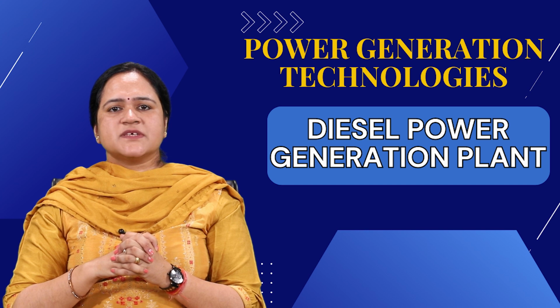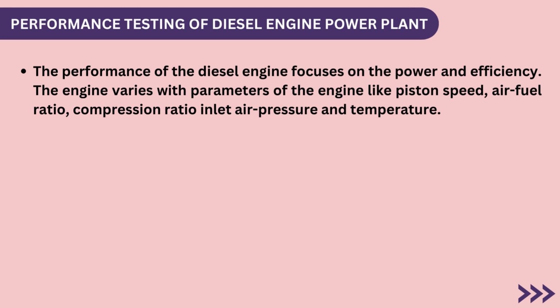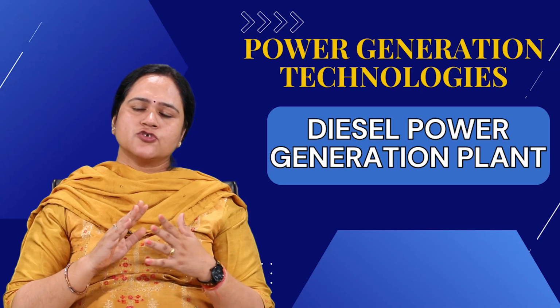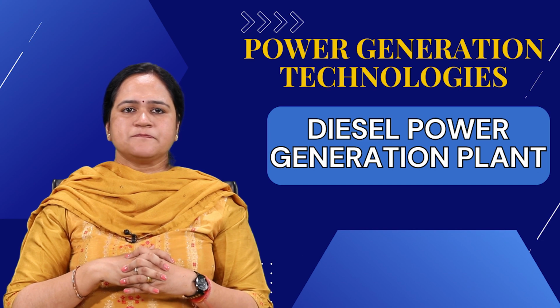Now comes the performance testing of diesel engine power plant. So the performance of the diesel engine focuses on the power and efficiency, and the engine varies with parameters of the engine like piston speed, air fuel ratio, compression ratio, inlet air pressure and temperature. So generally two usual conditions under which internal combustion engines are operated are constant speed with variable load or variable speed with variable load. So load will be variable always, either constant speed or variable speed.